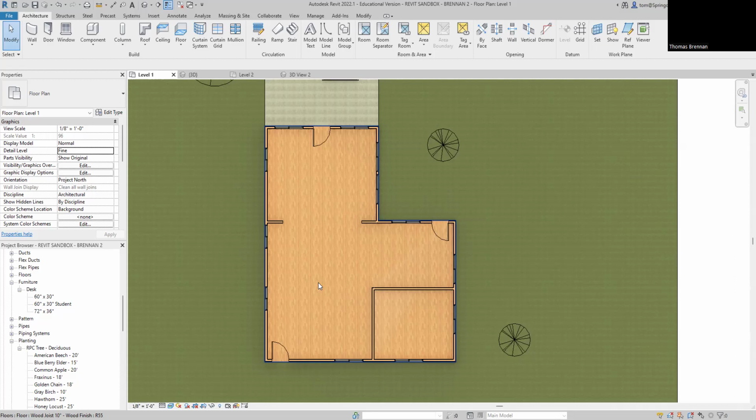I'm going to go to new. Hit the green check mark, and then take a look at it in 3D and see what you got. Okay, that's the hip roof. Everything's got a slope on it. And remember, we learned how to fix that. Click on edit footprint, click on one of the lines and remove the slope, and then do the other side too.